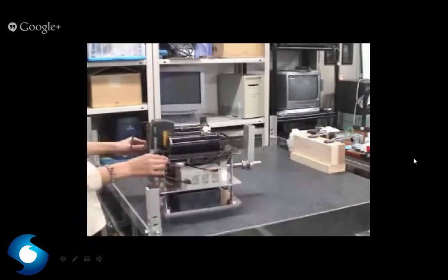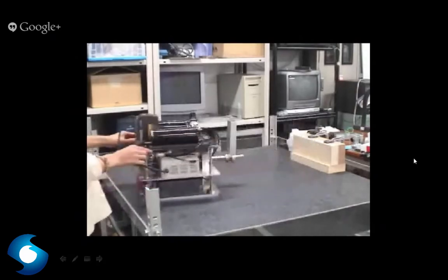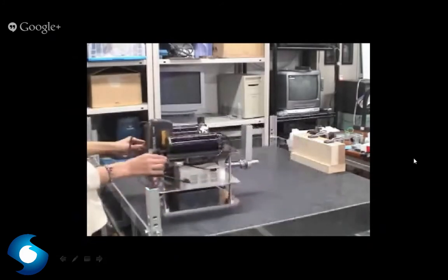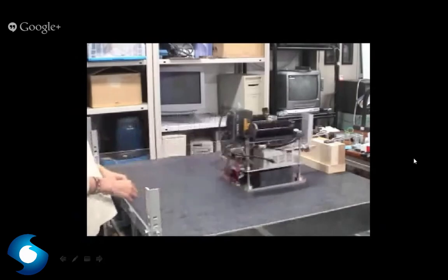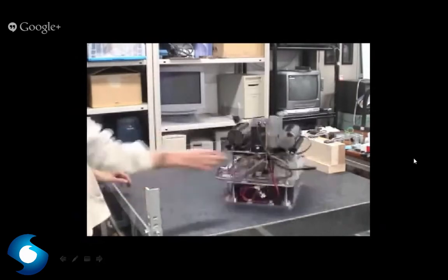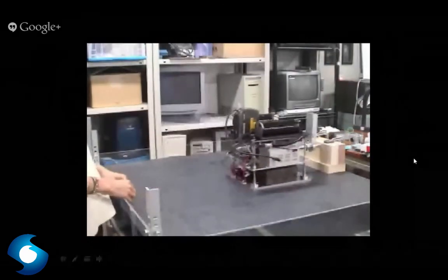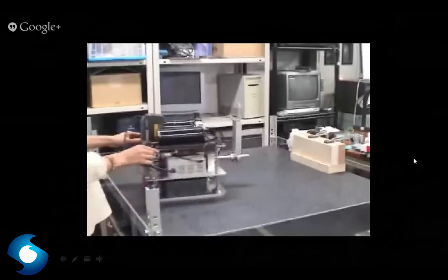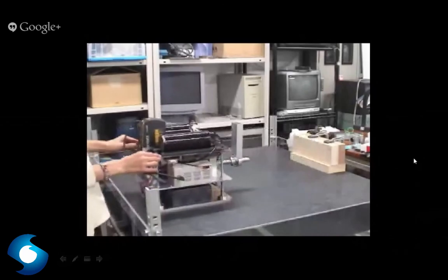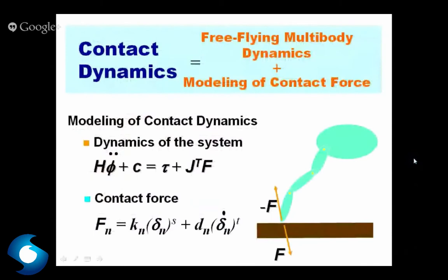we learn about the fundamental impact theory, and by using the coefficient of restitution, we get a very basic idea of the perfect elastic impact or perfect plastic impact or something like that. So to discuss the impact contact dynamics in a free floating manipulation, we need to go back to this fundamental physics.